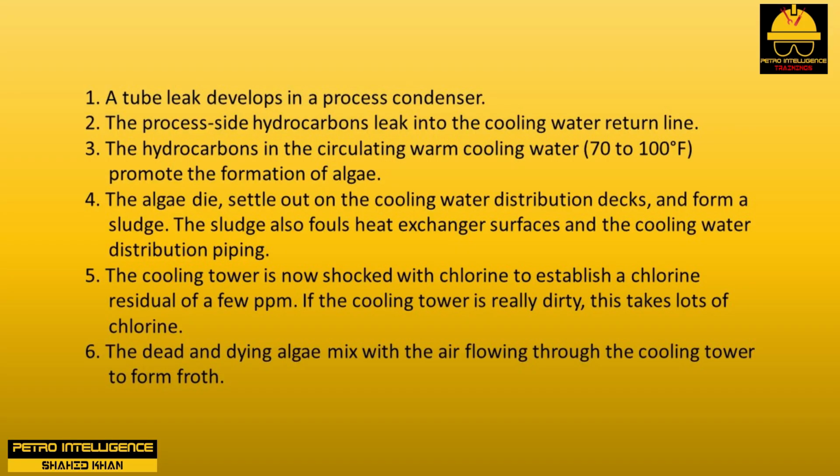Perhaps you have driven past a refinery cooling tower with frothy, white foam billowing from its top. That's caused by the following sequence of events. 1. A tube leak develops in a process condenser. 2. The process side hydrocarbons leak into the cooling water return line. 3. The hydrocarbons in the circulating warm cooling water, 70 to 100 degrees Fahrenheit, promote the formation of algae.